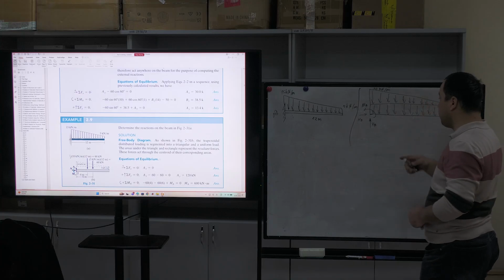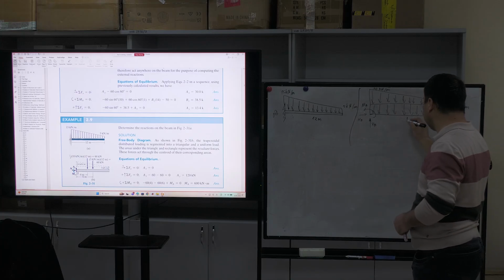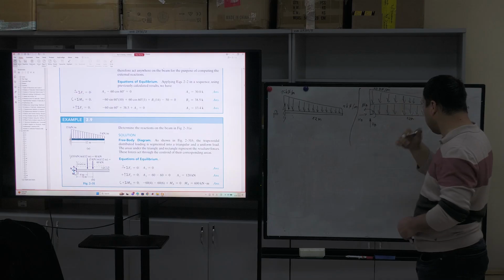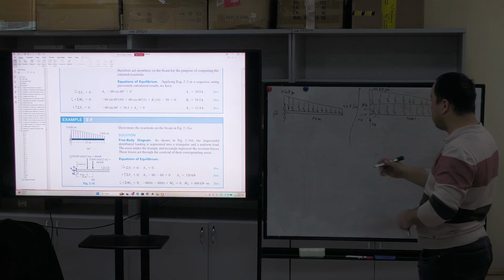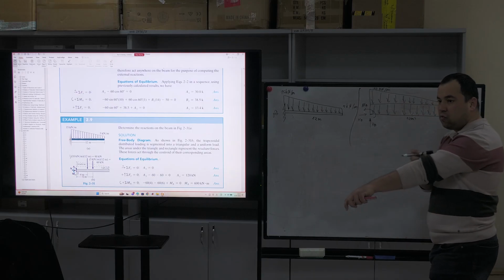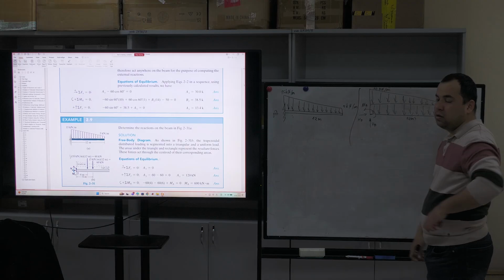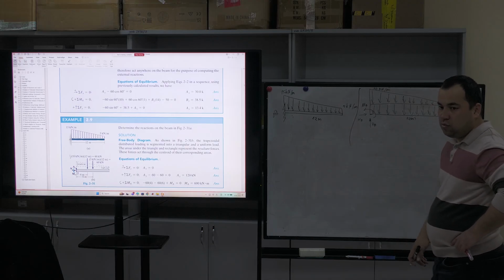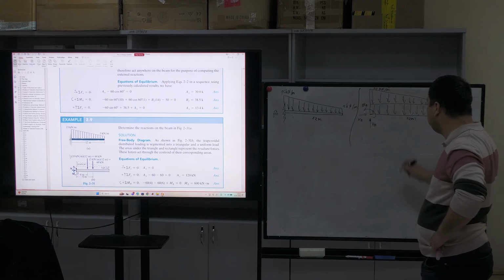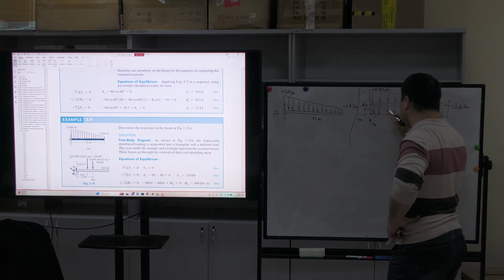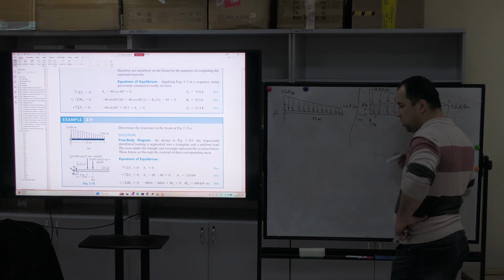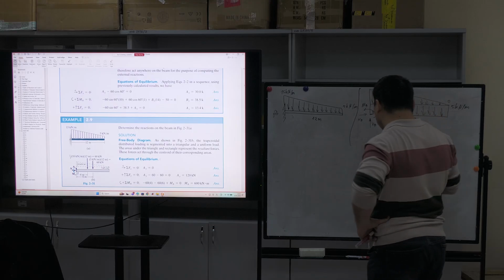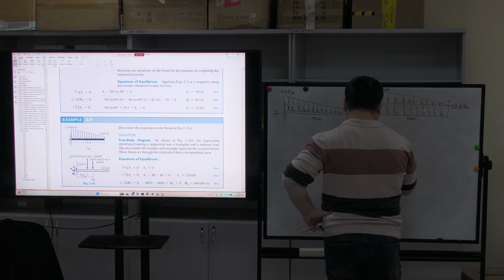Okay, I just separated it into two parts, 12 meters, and I have to calculate the forces, okay? Here, what kind of forces exist? One, yes, uniform distributed force exists. One is acting at 1/3 of this triangle, one is acting at half of the overall length of our beam, okay? Let's try to find the first force.